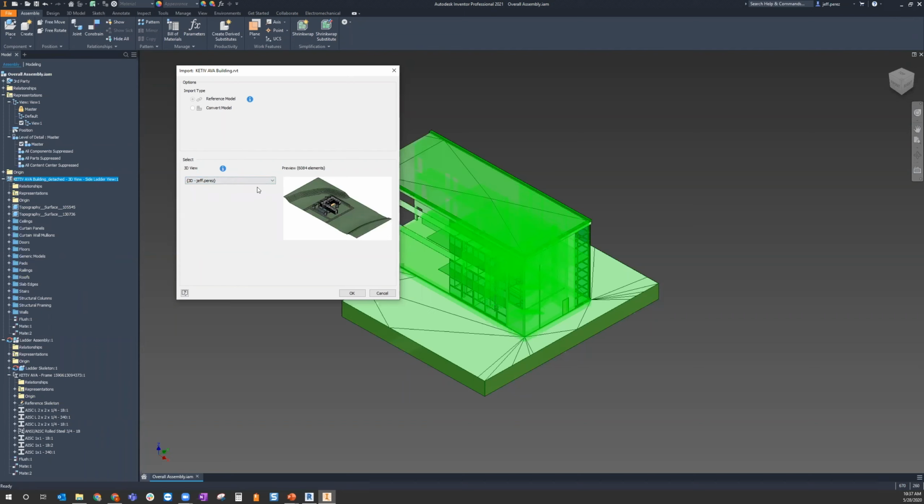What I would recommend is that you have your architect or whoever's creating these Revit files create multiple 3D views for you that you can utilize, so that when you're creating a brand new assembly, you can place in a completely independent 3D view to another assembly that you may have that may be utilizing, say, this 3D ceiling space view that I created early on. Okay. Hopefully that answered your question, Matthew.